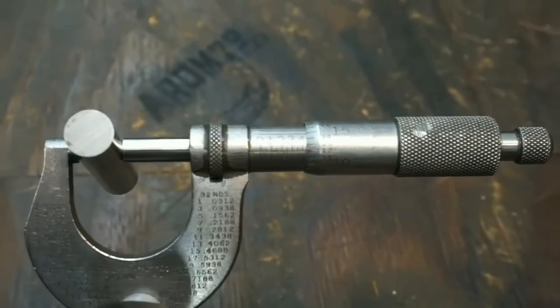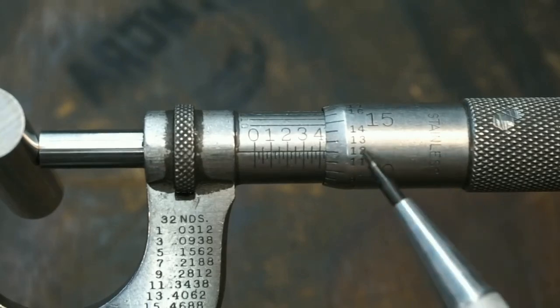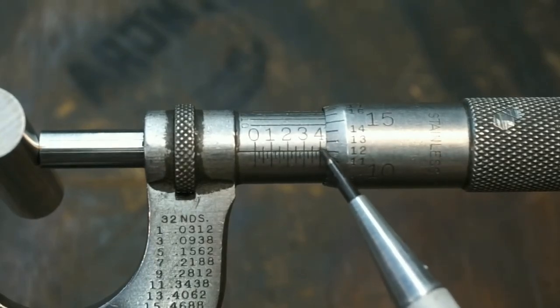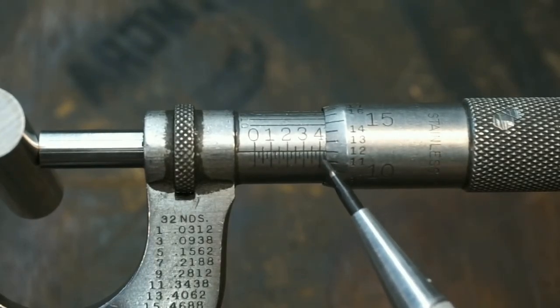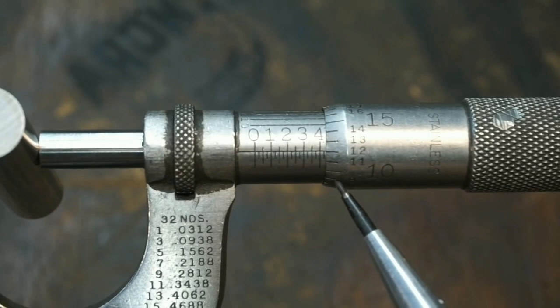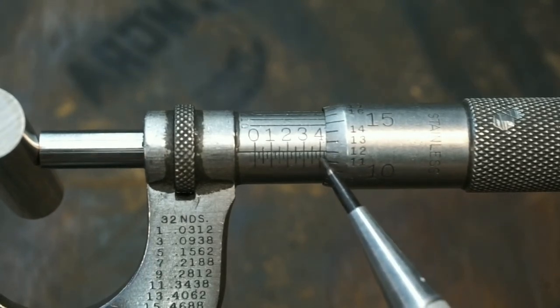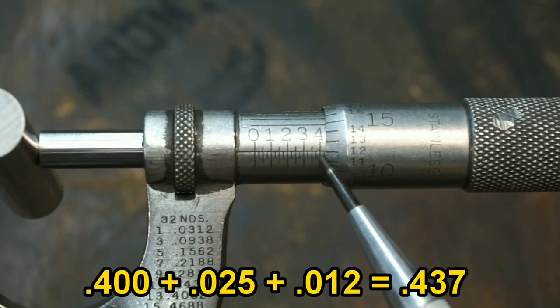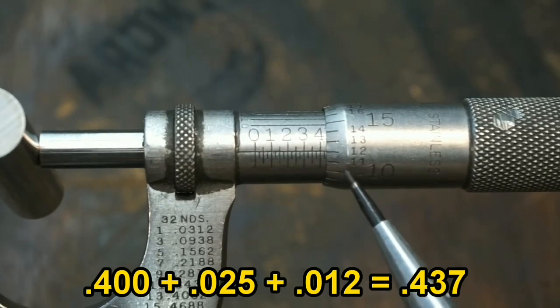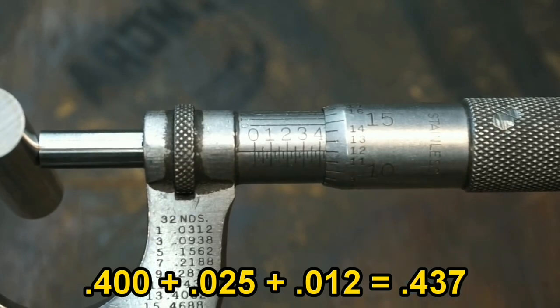All right, let's zoom in there and check out what it reads. So again, you already passed the 4, so go ahead and say 4.4. You already passed the 25 thousandths division there on the bottom. All right, and then you've gone around and you're lined up on the 12. So the way I read that is 425 plus the 12 thousandths. That's going to equal 437 thousandths once you add all those up.